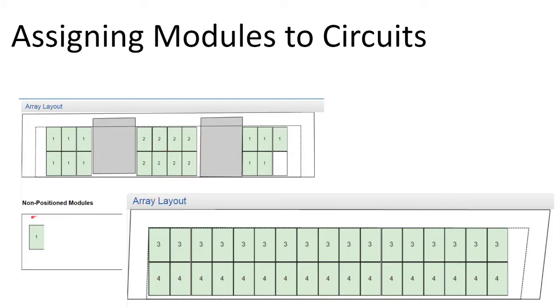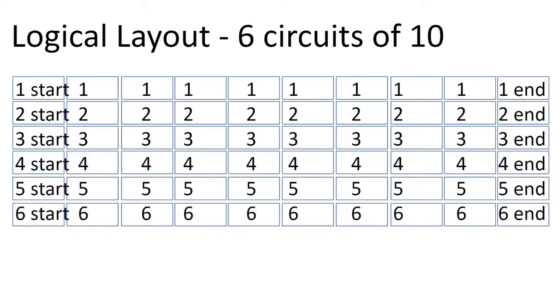Special care should be taken during installation to make sure these circuits are plugged up correctly. Having these locations planned carefully in advance will reduce mistakes in the field. I locate these connections at the corner of an array so that if they ever need to be inspected in the future, they are easily accessible.